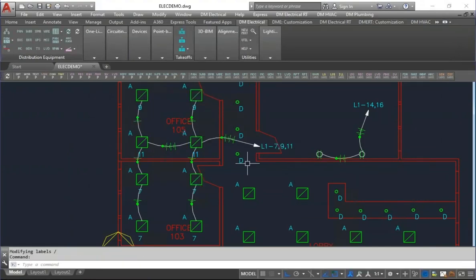If these are receptacles, you might want to connect them this way, but for light fixtures, particularly if they're actually switched, we connect here, and so we've got circuit 7 split between half of it's over here on the left, going through this light fixture, the other half is here, connecting up here. So that circuit is widely spread across this combined home run. So that's why you can join them first. So that's how you can control the default looping that Design Master gives you.